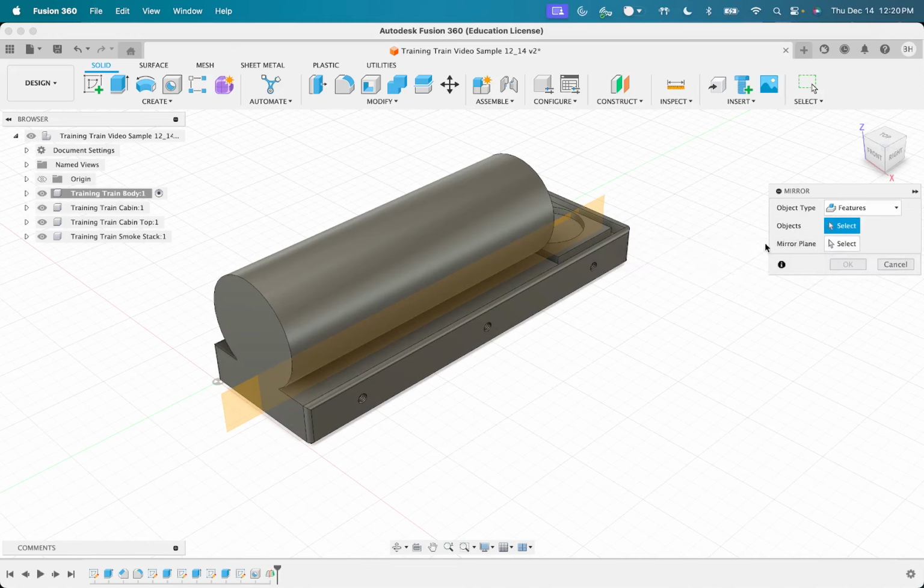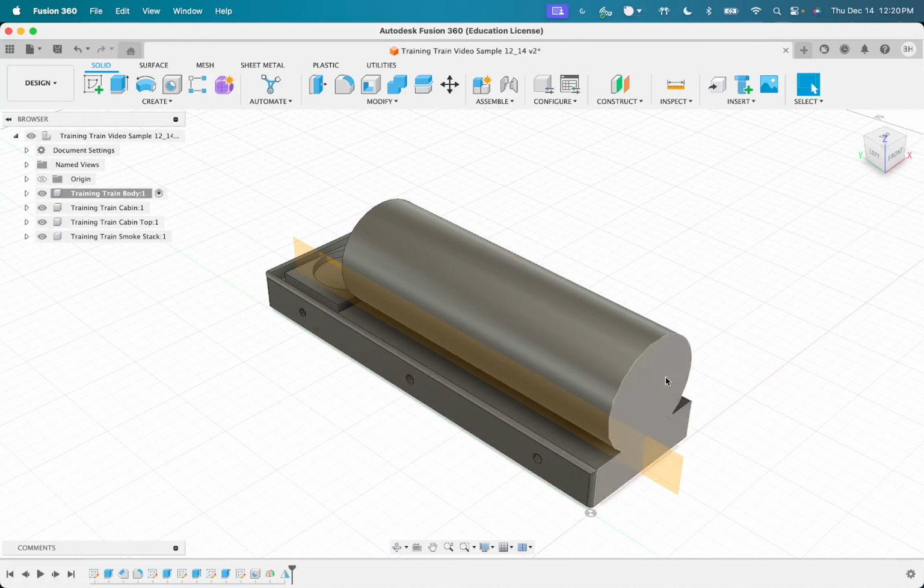Select it, and we can see if we go to the other side, it's going to cut these holes in for us. And compute type, for the case of this video, we're just going to keep it on just because that's the most basic one, and we don't need to talk about the differences between the others. So just click OK. And now we can see that we've done that. We have holes on both sides, and they're threaded on both sides.